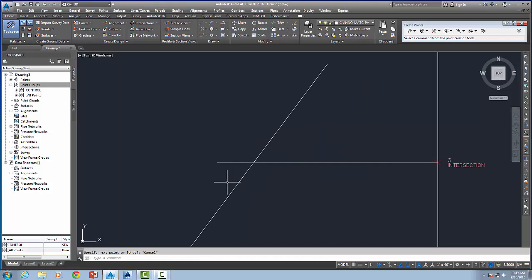So what we're going to do is just trim this off, and we could use an AutoCAD trim, but I find that fillet's a lot easier. I'm just going to type in an F, hit enter, generates the fillet command. Check your radius, R, enter, 0. Always set it to 0 because you never really know if it's truly at 0, so you might get a little arc if you don't. And I'm going to pick this guy and this guy, and notice it's gone.